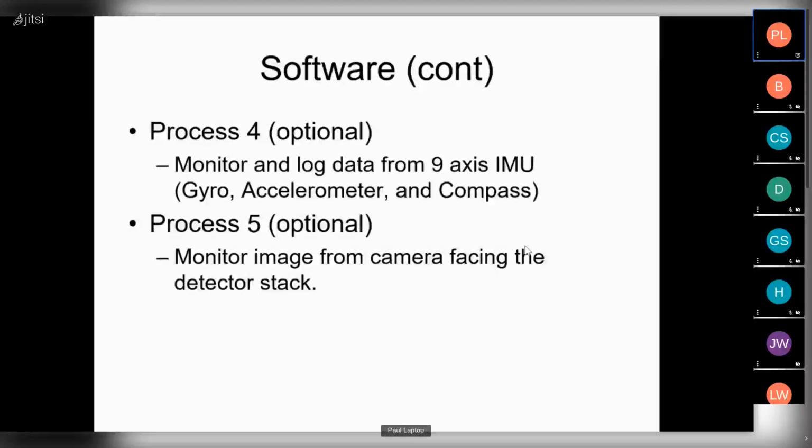Yeah. I have some ancient OPT101s, an old Burr-Brown transimpedance amplifier with a fairly large photodiode attached. I bought 8 OPT101s. I have not tested them. They're in 8-pin DIP packages. Yep, that's the part. You might want to look at these light curtains by STI or Banner. It's a similar problem. But the OPT101s I've used in a number of things, and they're one of my go-to parts.